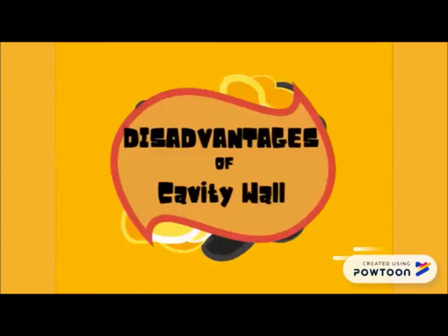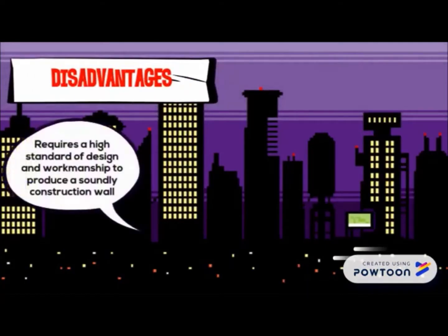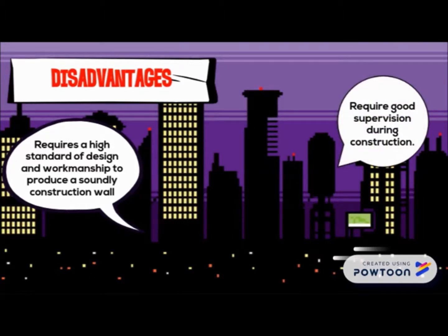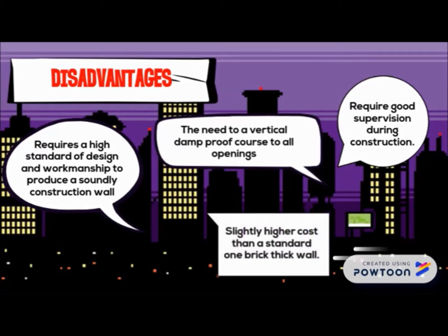So, what are the disadvantages? A cavity wall requires a high standard of design and workmanship to produce a soundly constructed wall, requires good supervision during construction, needs a vertical damp-proof course to all openings, and has a slightly higher cost than a standard one brick thick wall.